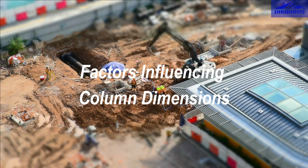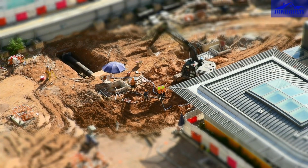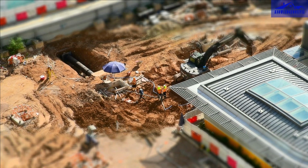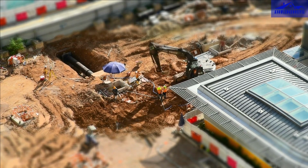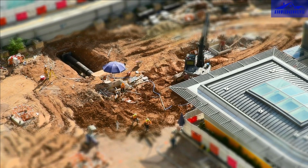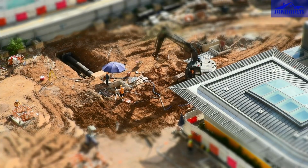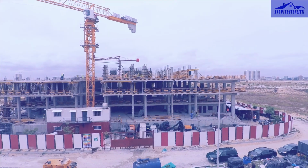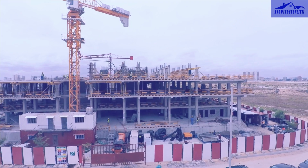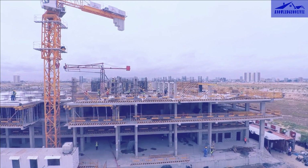It's crucial to understand how the number of floors, loading conditions, and column spacing play a role in determining the right size. As you increase the number of floors, the dimensions of your columns generally need to increase to handle the additional load. Loading conditions, whether it's a residential or commercial building, also impact your column size. And don't forget the center-to-center distance between columns, which should be between 3 meters and 5 meters.